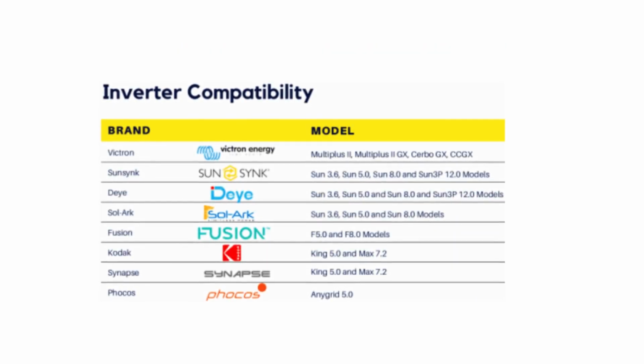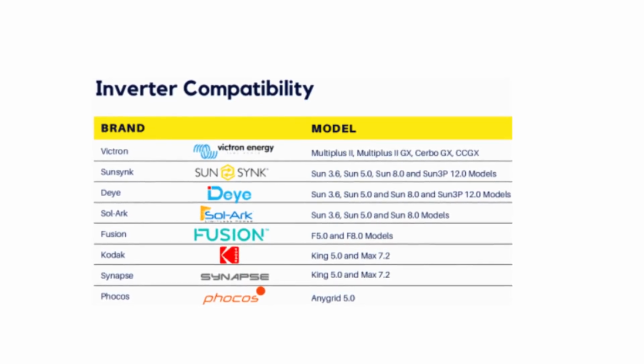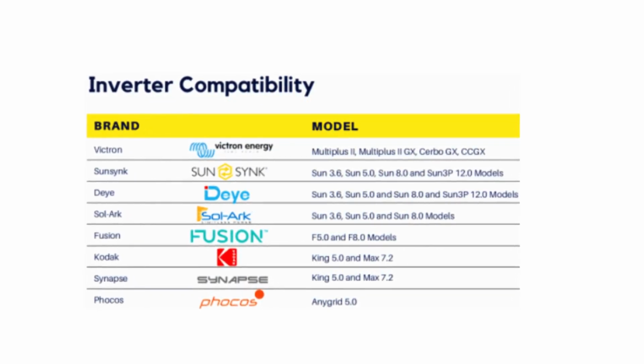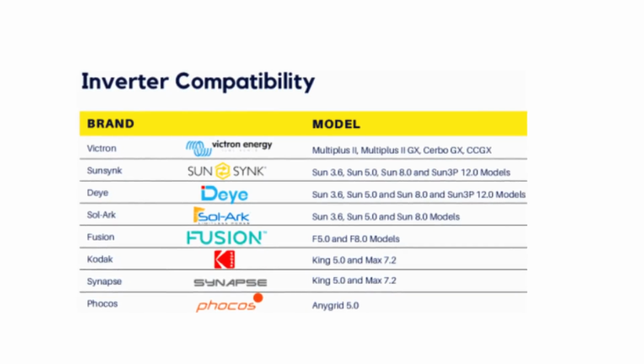Finally, double check that the battery you select can actually communicate with the inverter you choose. Both manufacturers can confirm compatibility.